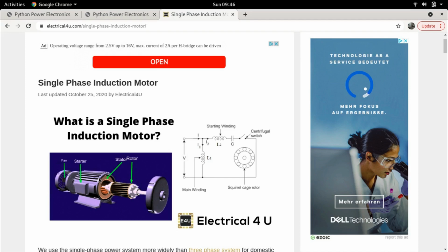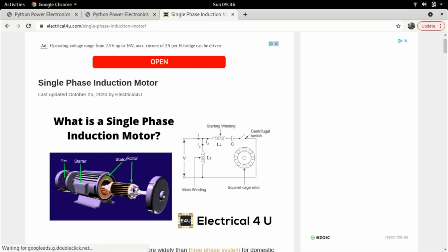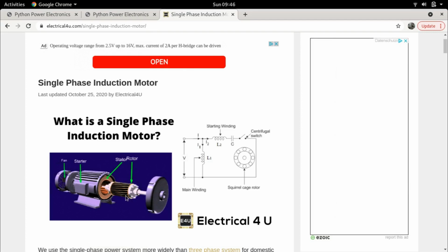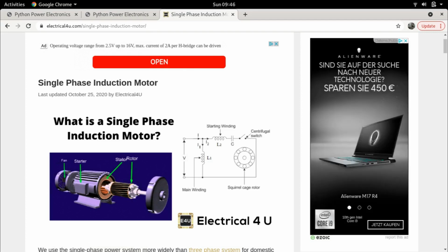So now the question is, if this machine rotates, what impact will it have on the stator and the rotor? The first and most obvious impact is that as the motor rotates and heats up, because whenever a motor starts working it will get warm, the temperature will rise. Therefore, with rising temperature, the stator resistance and the rotor resistance will also change. There is a temperature coefficient.